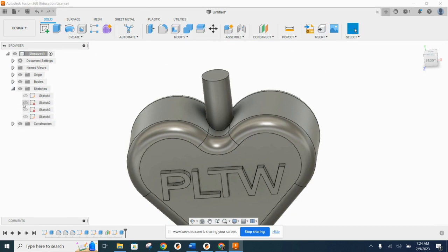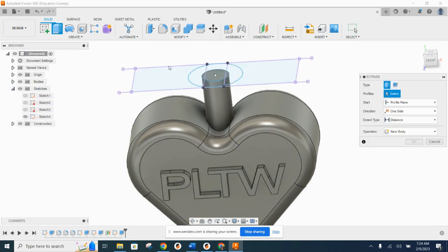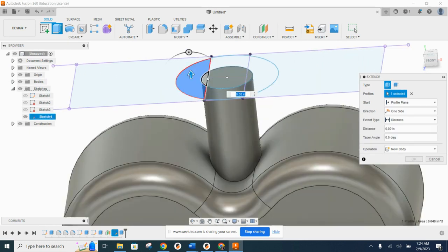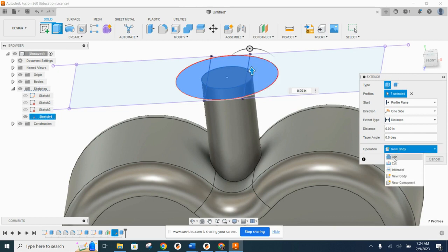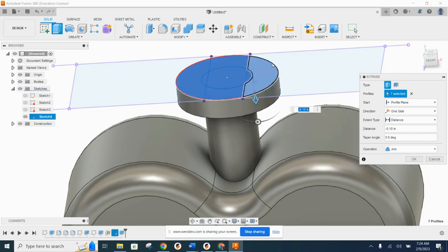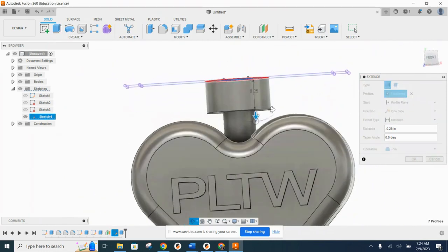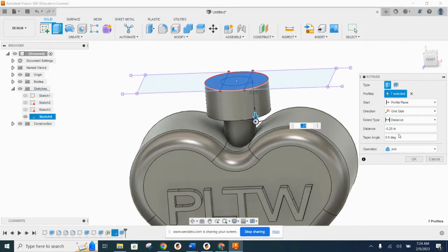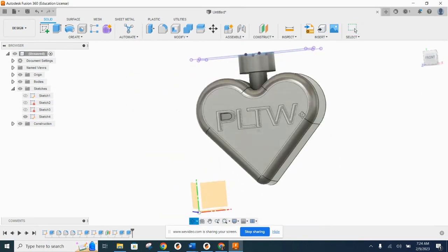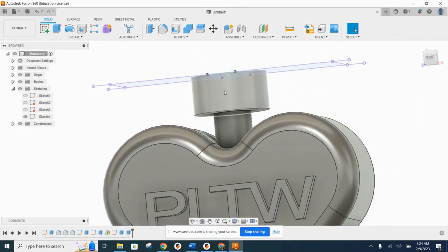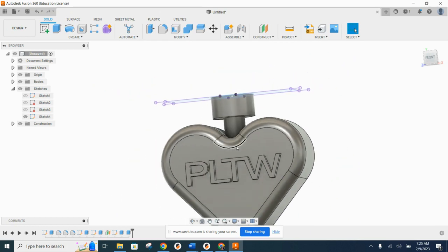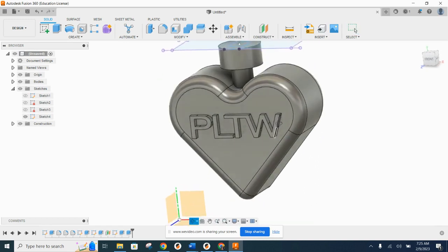I'm now going to pull that sketch back because what I also want to do is do an extrusion again of that entire profile. I want this to be a join, and I'm going to say that this is going to go in like a quarter of an inch. Okay, and I'm going to say okay on that. All right, so this is the nozzle coming off the pump. This is going to be the channel, the injection port where the chocolate's going to come in. This is the cavity that the chocolate's going to go into.